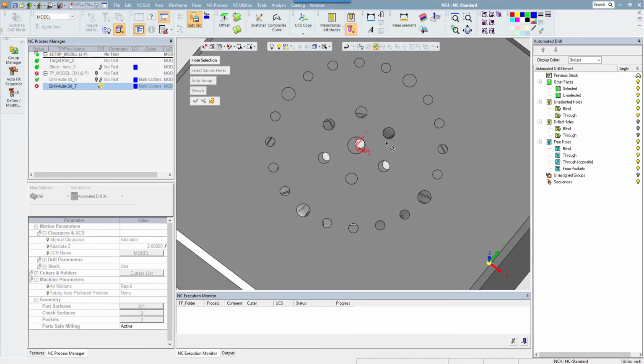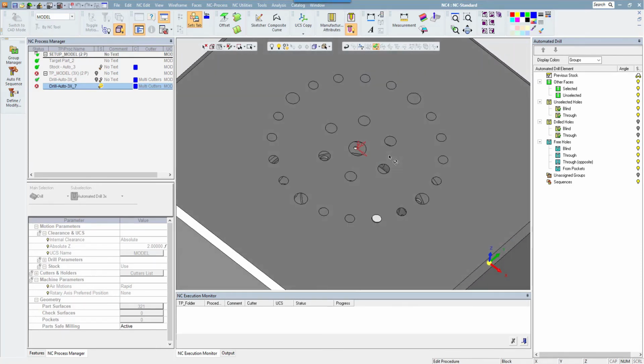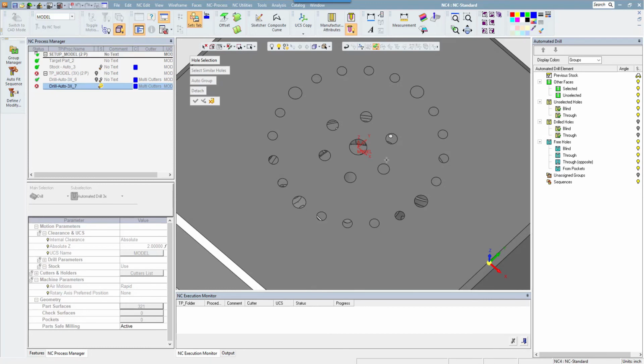Well, the system knows that you could have and did do these holes, or at least pick them in groups in the previous procedure. So why would it put them here for you to keep drilling the same thing over on a large part that could create a lot of work picking through things? So they recognize that it was drillable in the previous procedure.